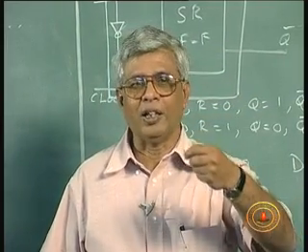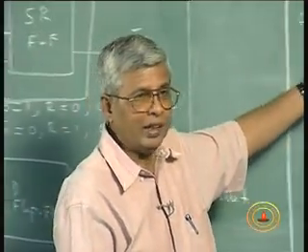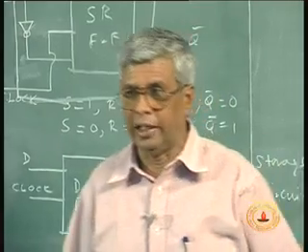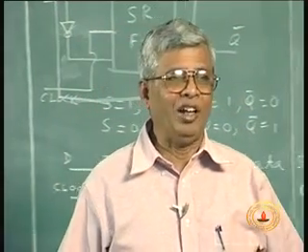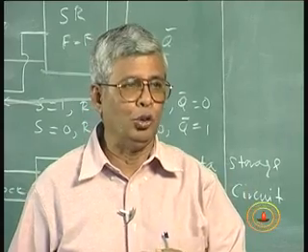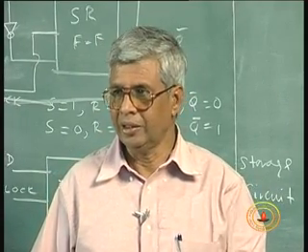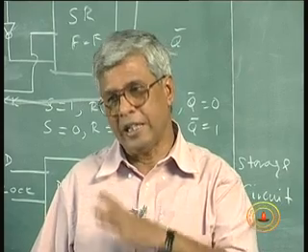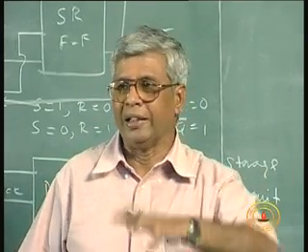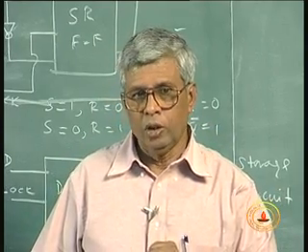Whether it is too small for us, 1 nanosecond, let us say a couple of nanoseconds for this gate, another 2 nanoseconds for this, 2 to 3 nanoseconds per gate, a total of 5 nanoseconds, let us say. Every 5 nanoseconds the output changes from 1 to 0, I can't do much with this, right. So, I would like to have it change but in a more orderly manner, at more regulated intervals. There are two things you can do.